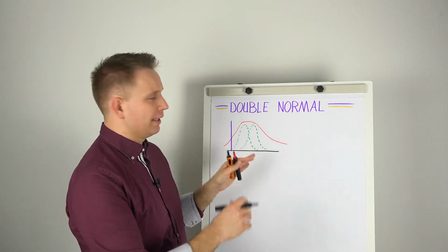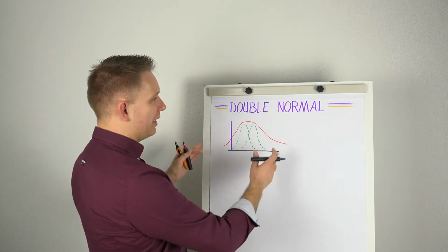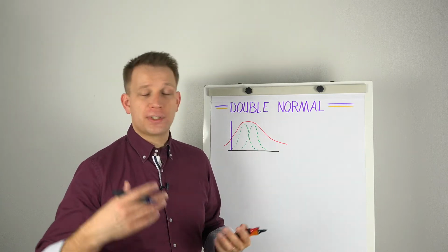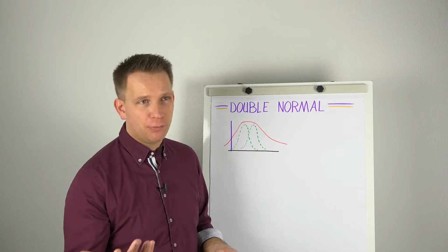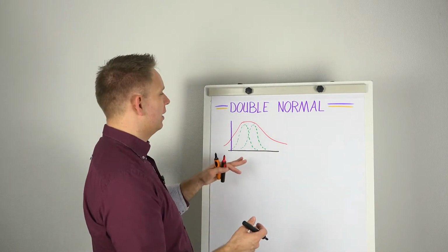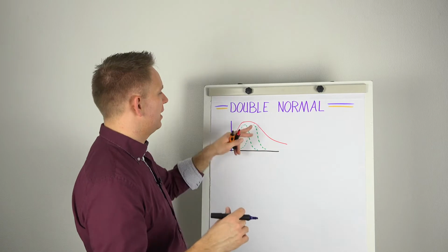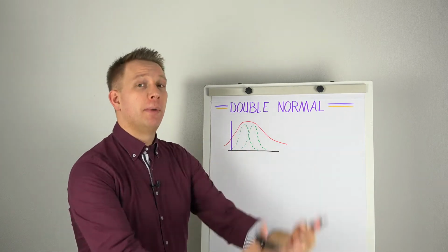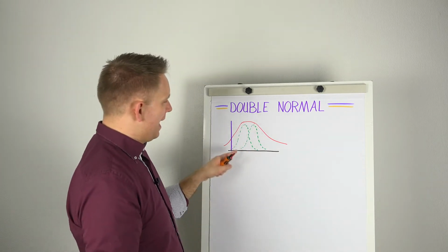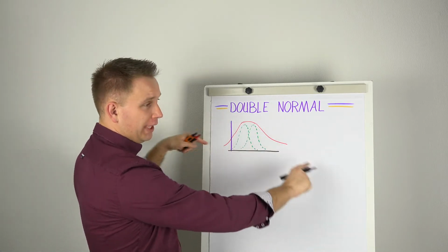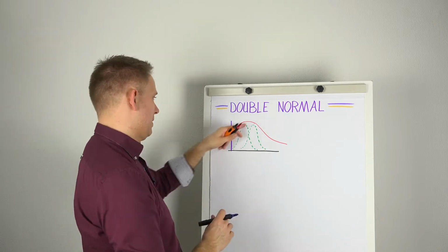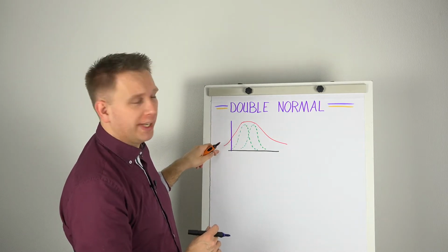If we take the average weight plus the standard deviation, and then we say, for instance, we want 3 standard deviations to be relatively sure, so that's a CPK of at least 1, 3 standard deviations, that we are above the limit, then we have to move this whole thing, because the 3 sigmas, they say, well, you have quite a way to go.